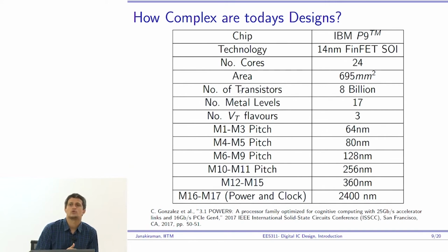It's about 1,000th, 10 power minus 3. That's what a technology can guarantee. Beyond that, it's very difficult, right? So they found it very difficult to achieve this beyond 22 nanometer with the old transistor technology. They had to move to FinFETs, okay? And that is basically some 3D structure. I'll try to just tell you at least what that structure looks like at some point when I do the transistor. But let's just take it for now.